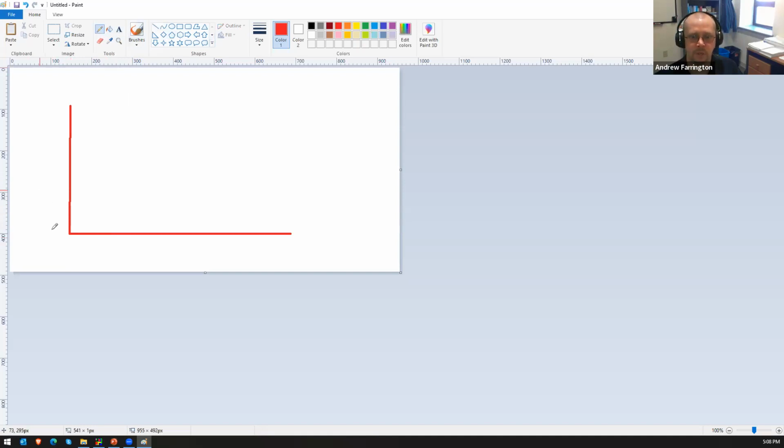But I guess, this is the operate current, apologize for the artistry, IOP. This is IR, restraint. And it usually looks like this. So it's flat down here, the linear region, and then you get to slope 1, and then slope 2. And this should look very similar to what Brandon went over a couple classes ago, which is why I didn't bother to cover it again, because fundamentally it's the same thing.